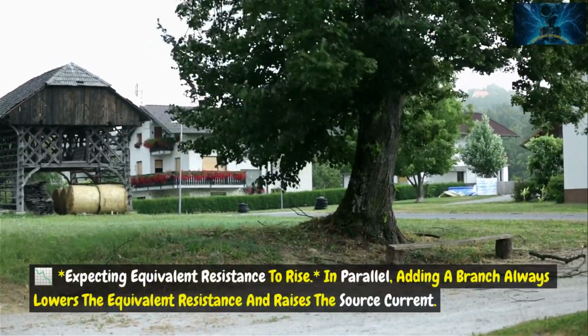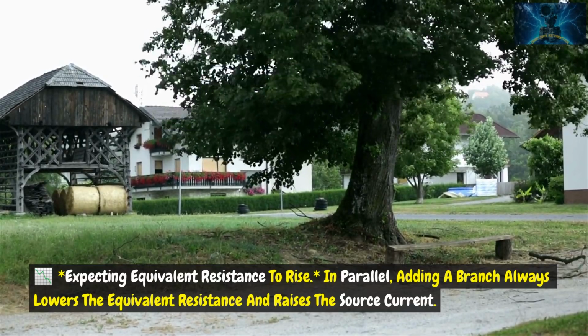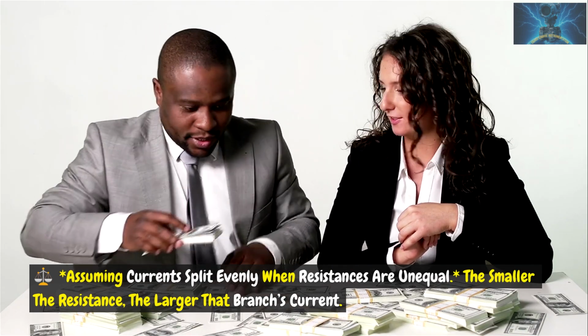Expecting equivalent resistance to rise. In parallel, adding a branch always lowers the equivalent resistance and raises the source current. Assuming currents split evenly when resistances are unequal. The smaller the resistance, the larger that branch's current.